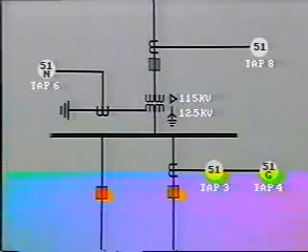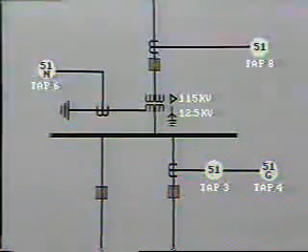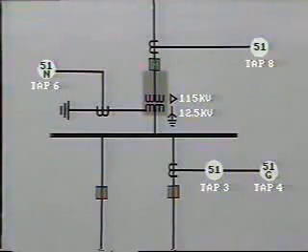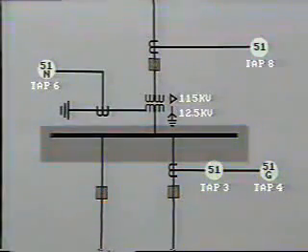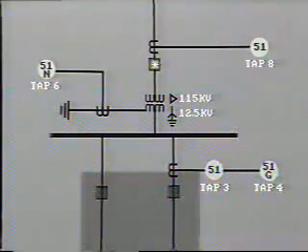Another arrangement here shows a circuit breaker on the primary with the secondary connected directly to a bus. Each feeder has its own circuit breaker and individual protection. The primary circuit breaker will trip for a fault in the transformer zone, or a fault on the bus, or a fault on any feeder which fails to be cleared by its own primary protection. Because of its inverse time characteristic, overcurrent protection is well suited for backup application, but for protection against internal faults, more sophisticated schemes are required, particularly on large transformers.